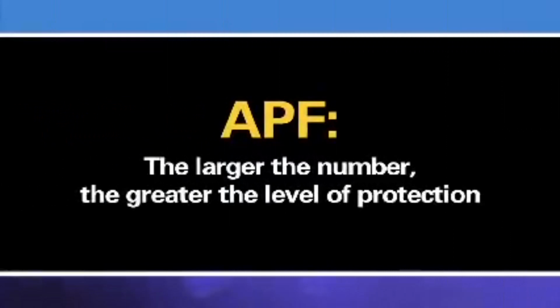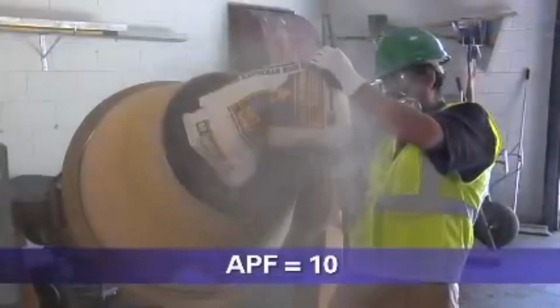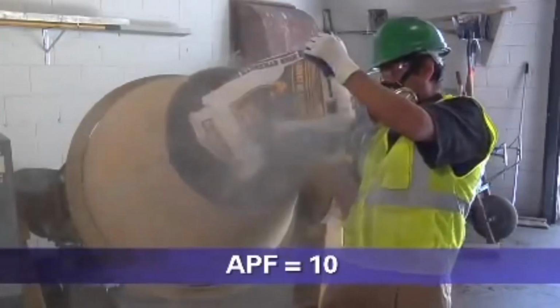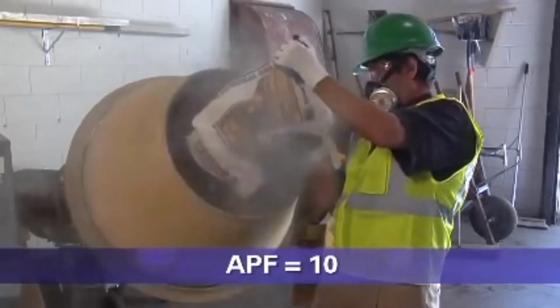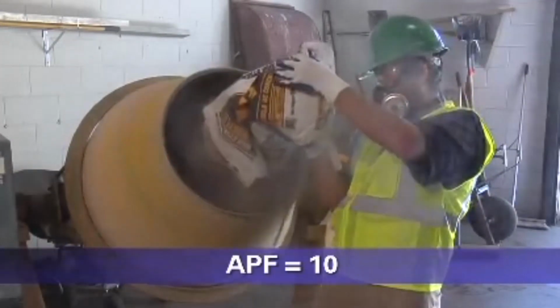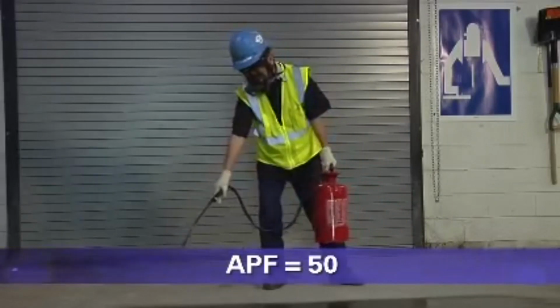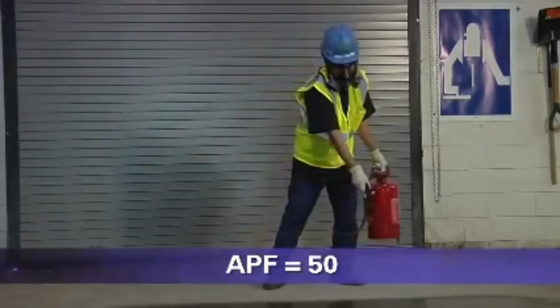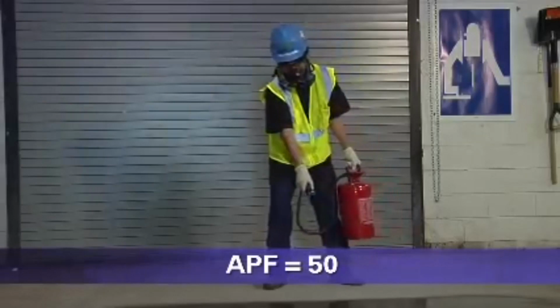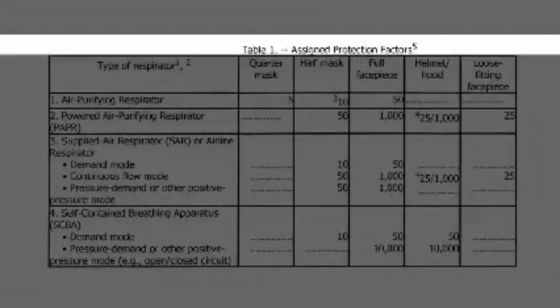The larger the number, the greater the level of protection. For example, when used properly, a respirator with an APF of 10 will reduce your exposure to 1/10 the concentration of the contaminant in the air. Similarly, a respirator with an APF of 50 will reduce your exposure to 1/50th the concentration of the contaminant in the air. OSHA's APFs can be found in Table 1 of its Respiratory Protection Standard.